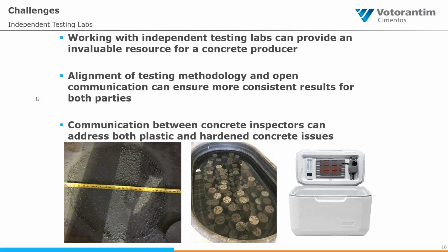these mixes, even if you are targeting massive concrete considerations as well, have a tendency to be run very hot and to break down within the cylinder on their own, self-desiccate, other sort of natural striking features that you don't see in traditional concrete. So trying to head that off in pre-pour meetings, in initial testing evaluations is a great way to save yourself headaches and a lot of time and labor spent in trying to solve the issue of concrete that's not actually defective.